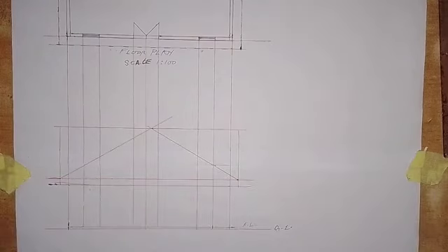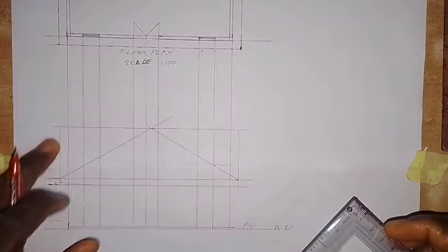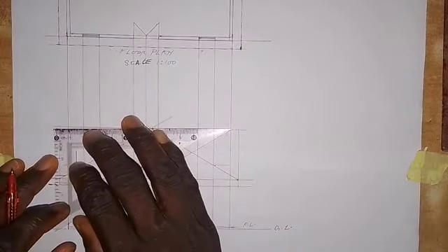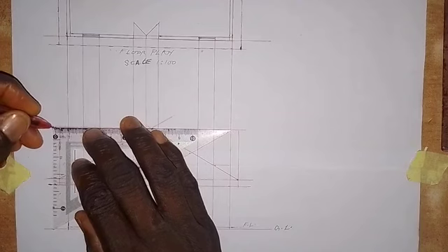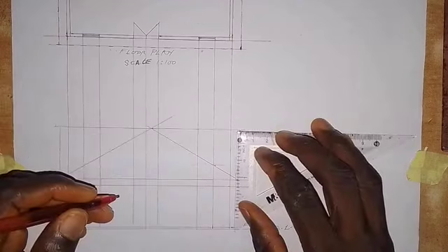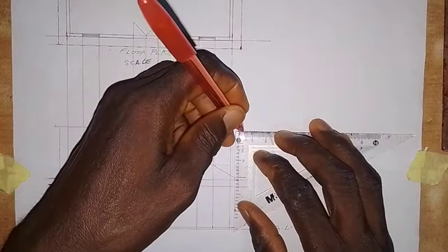Now, if you look at the roofing material, it goes a little bit beyond the ceiling. Just go outside your building and look at the distance between the end of the ceiling and the roof. There is a little distance between them. So the roofing material goes a bit beyond the ceiling itself. That is why we extended this line and this line. That little distance, I'll just make it 30 millimeters. So take a measurement of 30 millimeters to this side, and on this line, I do the same thing here, 30 millimeters to this side.